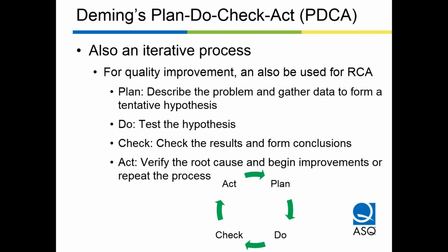I say in root cause analysis, it's okay to be wrong. You just want to be wrong as quickly as you can, and I will qualify that with in the most economical manner possible. If you have two hypotheses and one is more probable, generally you test that first, but if the more probable one requires $100,000 in testing in a three-month test cycle, and the other is measurement deviation I can check with calipers, check that one first.